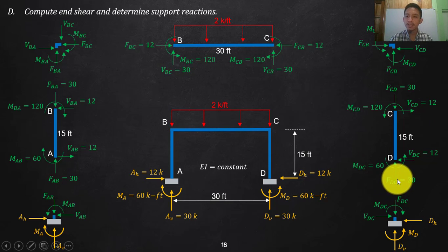Now how do we get again your axial forces? All you need to do is transfer your end moments and end shears onto your joints. For this joint we will of course not transfer to the support yet, since later on, when we know everything on the axial, shear and moment of this, we will transfer to that support so that we will get the support reactions.